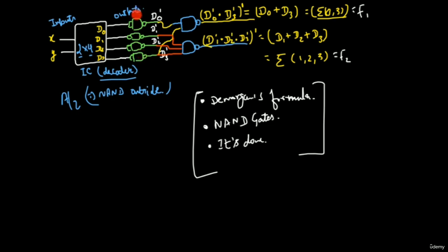So first we complemented all these things and then combined and then again used the NAND gate, because the NAND of the NAND, if you remember recalling the thing we have studied, a complement's complement is actually the element A. So the NAND of the NAND, if you give the input A, it becomes A dash. Now A double dash actually becomes A.